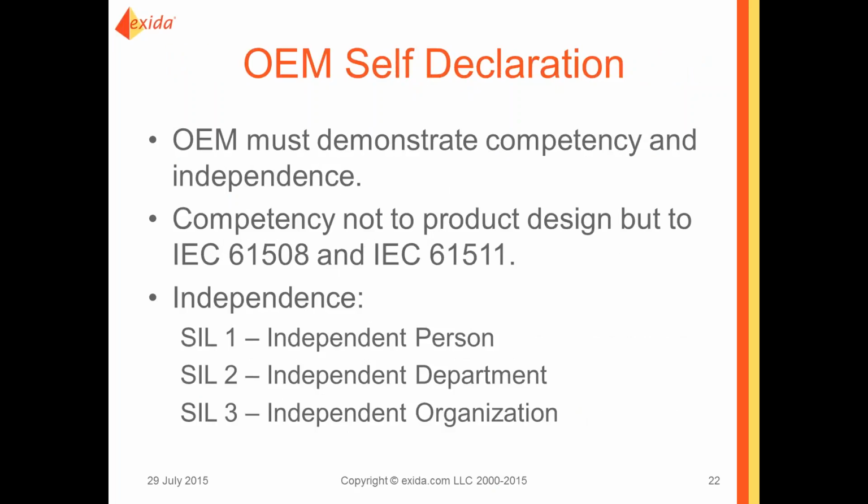Another thing is OEM self-declaration. Some OEMs have issued certificates and self-declared they meet a SIL level. So the OEM must demonstrate competency and independence. The competency is not in the product development of what they're doing, but in functional safety to the standards of 61508 and 61511. And for the independence, there's guidance in 61508.